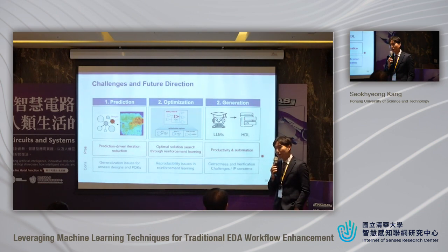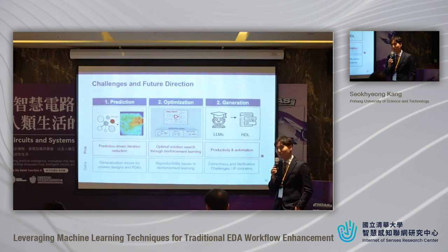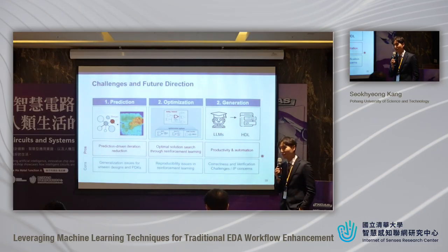We use pictures from the layout, the congestion data and the timing data, and we divide the layout into small grids. Inside each grid, we use data such as how many standard cells there are and the utilization. Such data is used by some tool to find design rule violation patterns. Right, that's right. Okay. Thank you.